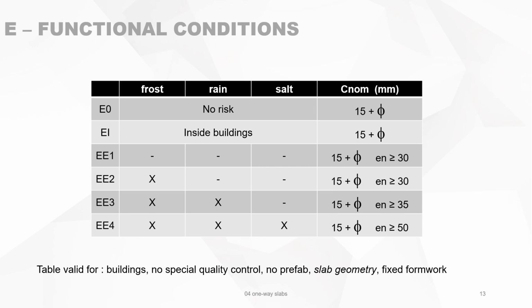You can put this in a table. You can combine it in one table. And for instance, you can see that for inside buildings, most commonly used for offices, for instance, then you have a concrete cover of 15 plus the maximum diameter.